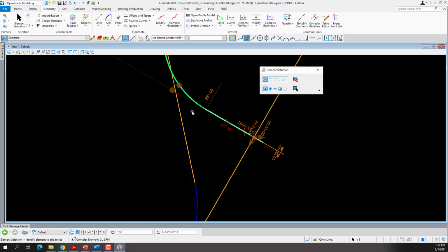We can come, double click, we need a backup if we need a backup. Your alignment file is changed in FDOTConnect to where your horizontal and your vertical will now live in that file. So your alignment file is a living file. It's just not for text or your stationing ticks anymore. It's your actual horizontal, you're controlling alignment, both horizontally and vertically. But if you do need to save a backup, which is a good process to get into, is to back